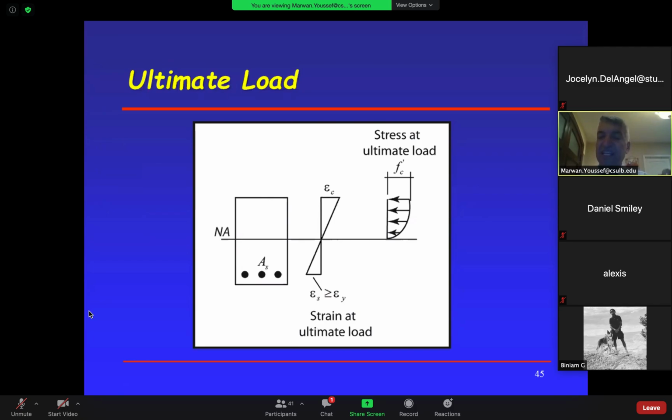And the force is going to lead to a stress and a strain. Again, F equal E times epsilon. Now, the E we're going to use for the steel is not the same as the E for the concrete, because the E for the steel is 29,000 KSI. Different than that. Depends on the material. Again, we're going to see it a million times.